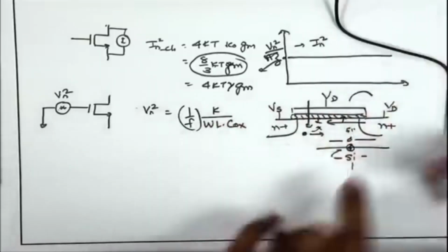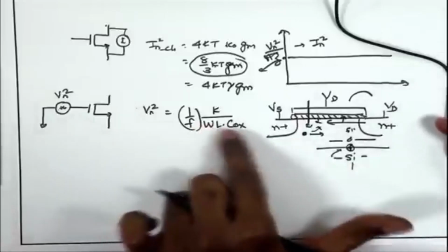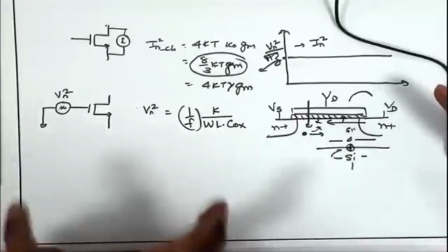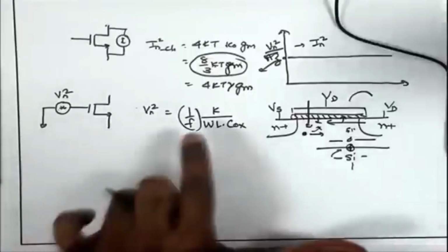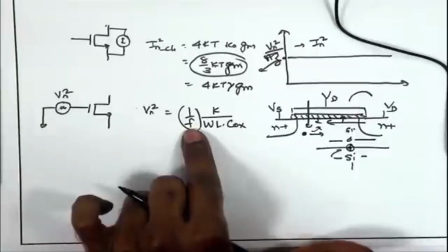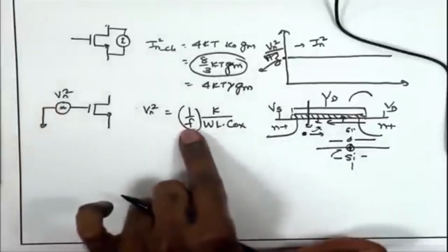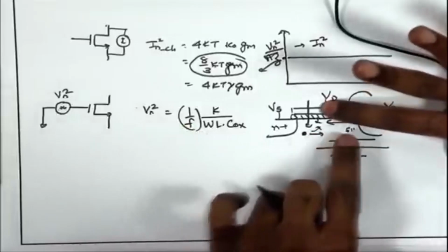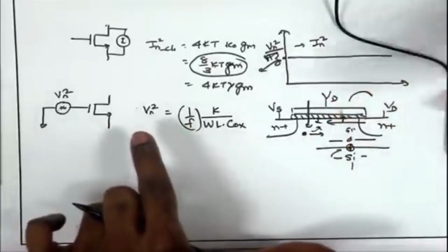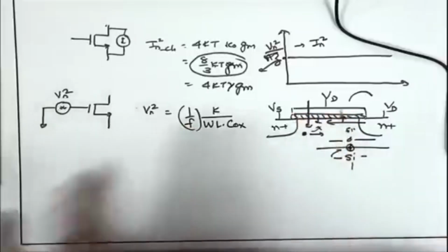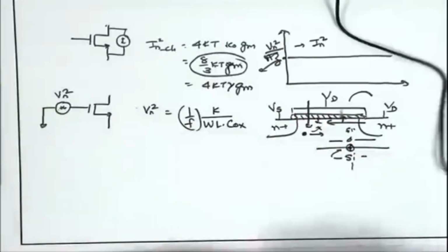So, if I want to find out total charge integrated because of this trapping detrapping phenomena, it will increase if we integrate it for a longer time or a longer duration. That means, the corresponding frequency spectrum is lower. If I observe this noise for a longer duration, the amplitude will be integrated. This trap detrap charge integrated over a long time will give me larger change in the threshold voltage, larger change in the charge accumulated, and therefore, this 1 upon f noise comes into picture.